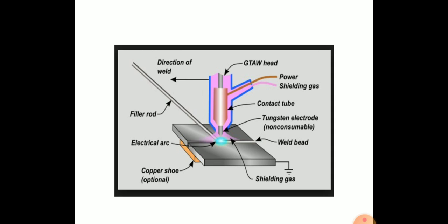Disadvantages of TIG welding: tungsten if transferred can contaminate the weld pool. If the filler rod by chance comes out of the inert gas shield, it can cause weld metal contamination. Equipment costs are higher than flux shielded metal arc welding. The electrode is non-consumable, so a separate filler rod is needed, so there is a decrease in welding speed.